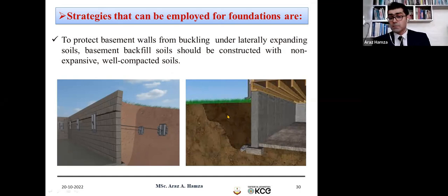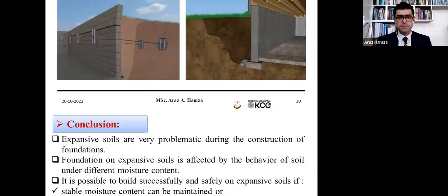Also, in some developed countries, they use granular plastic to fill such a project for the backfilling process. Why? Because plastic or other such materials are lightweight, and they do not put pressure on the wall, and also they are not expansive. This is another idea for backfilling.